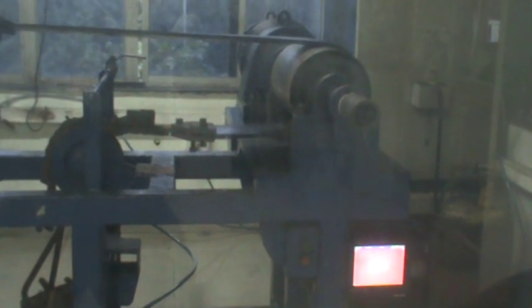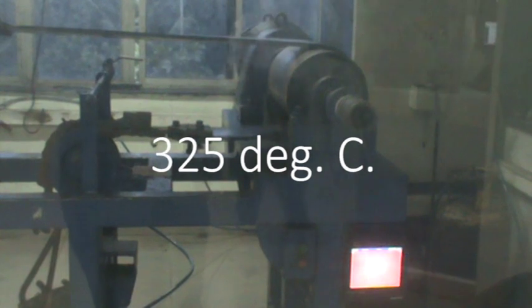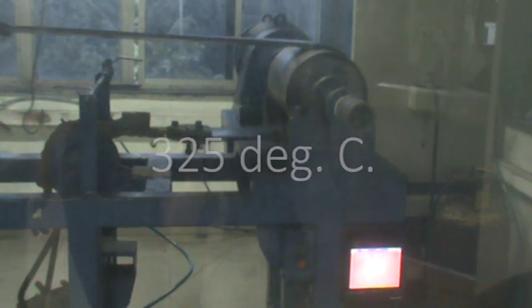Depending on the standards used, the temperature is not allowed to go above a certain set limit. In the case of AS 4606, the maximum temperature allowed is 325 degrees Celsius. Testing is usually conducted on the top cover and then also on the bottom cover. In addition, the testing is conducted once using a jet to blow compressed air onto a belt to simulate a draft which may be present in mining shafts. Therefore, testing is specified as being with or without air.